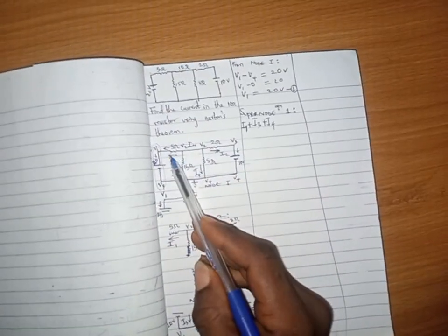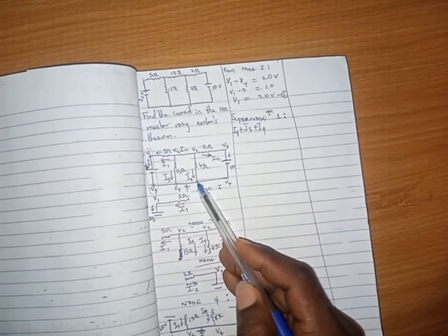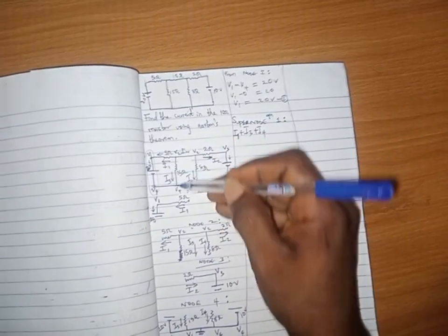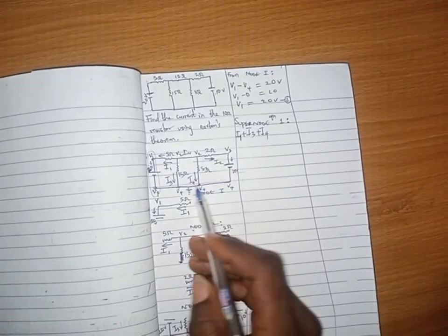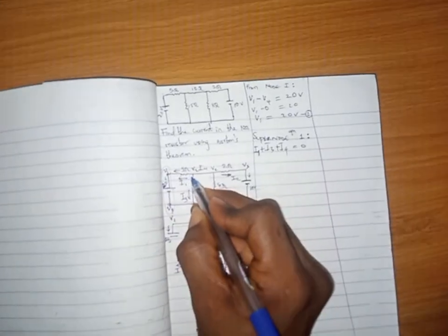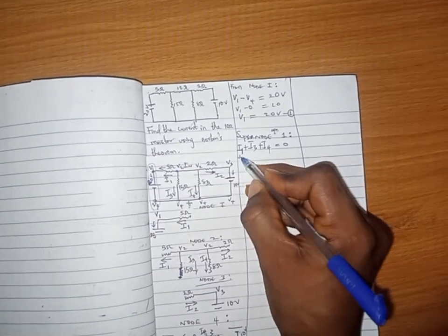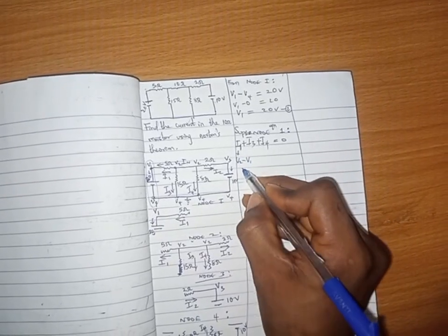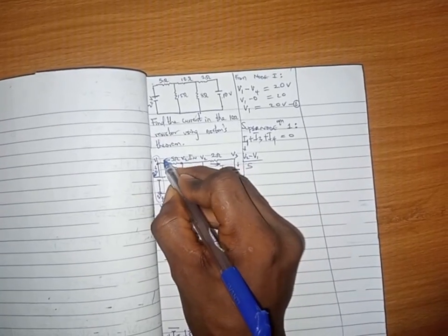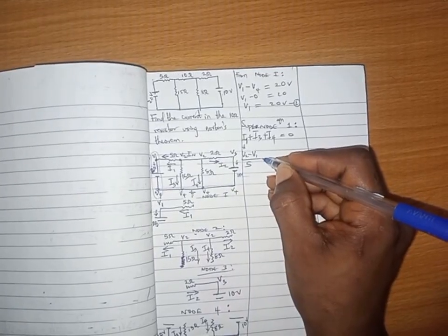You can see that if this is the node, this is the node, if this is node V4, what are the currents entering? This is entering it, this is entering it. So that means that is equal to 0. So now let's check something. I1 that you have here is in between V2 and V1. So you say V2 minus V1, all over what is the resistor in between? 5. Why am I saying V2 minus V1? Because see that the direction is this way. So V2 minus V1. It moves from upper to lower, higher potential to lower potential.